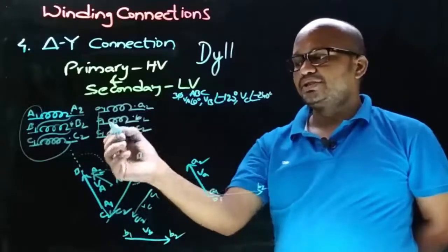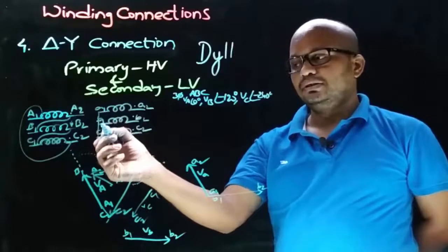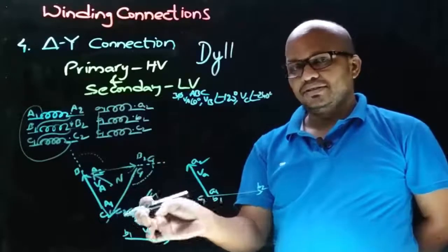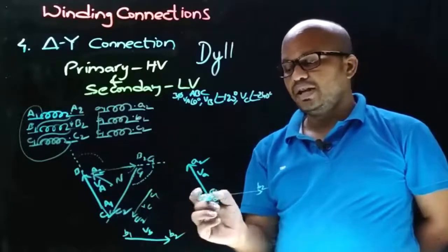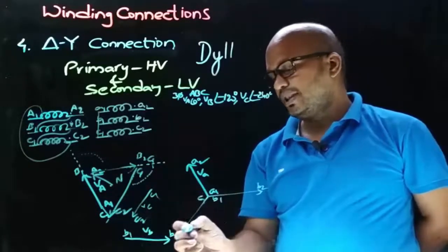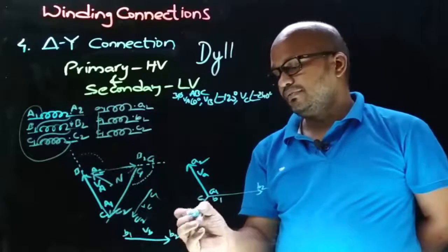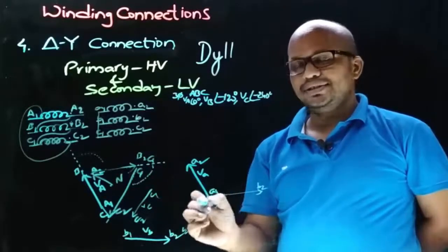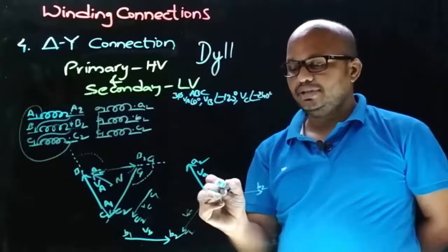And observing the winding connection, to A1 and B1 there is a C1 connection, means here we will get C1. So draw this phasor such that A1 and B1 will have the C1 terminals. So like this. This is the VC phasor and the end will be C2. And now let's give the common notation for this common connection. Let that be small n.